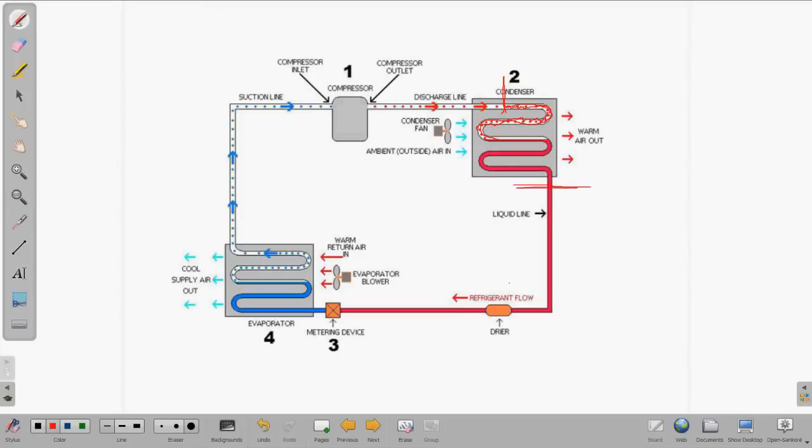So that's a quick down and dirty check: your subcooling, always. If you have really high subcooling, you have a pretty good indicator that it's an overcharged system. And then you go in and ask, what is it, a fixed metering device? So I'm looking for little to no subcooling. You don't even need to look at it.